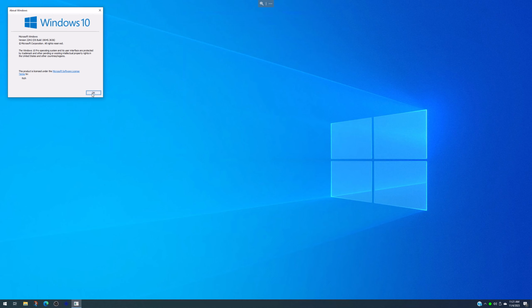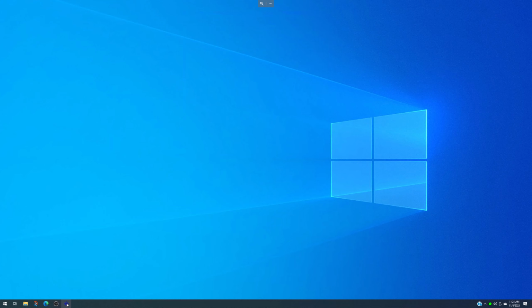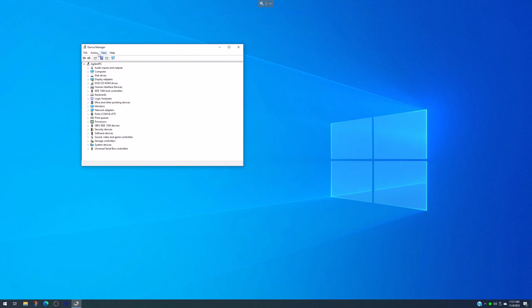Basically, you need to get an operating system up and running and then load up this Agilent software, which I'm going to open in a minute. Now, I've seen a lot of posts about, can you run a newer operating system than Windows XP, which is probably what was used when this software first came out that I'm going to use. And you definitely can. I'm running Windows 10. I would maybe point out just a little bit here on that. If things are working correctly, if you have a FireWire card that is supported by the logic analyzer, it should show up under logic analyzers, and then here you can see this PC is detecting an Agilent 1680/1690, and that would be connected through a FireWire controller, which here is my FireWire controller.